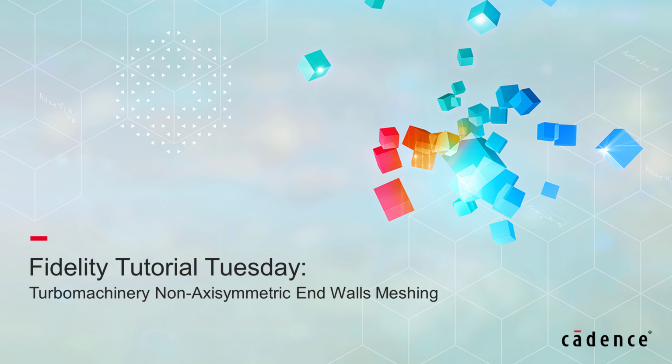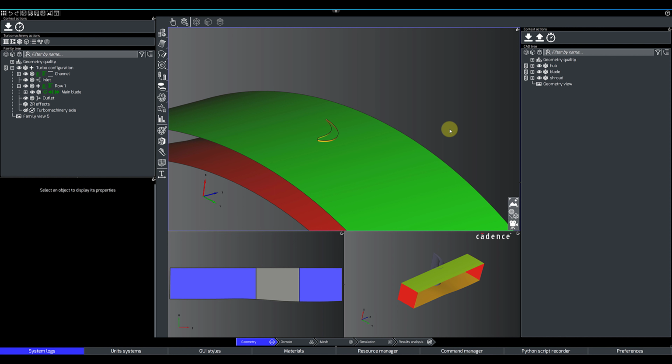In this video, I'll cover the main features linked to Turbomachinery Non-Axisymmetric end walls meshing. Fidelity AutoGrid allows meshing non-axisymmetric end walls in two steps. First, an axisymmetric mesh is generated. Second, the axisymmetric mesh is adapted to the specified non-axisymmetric end walls.